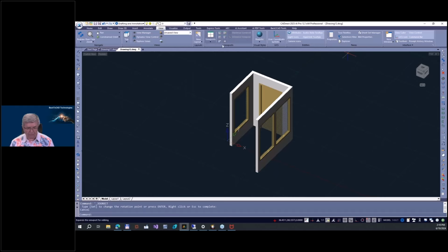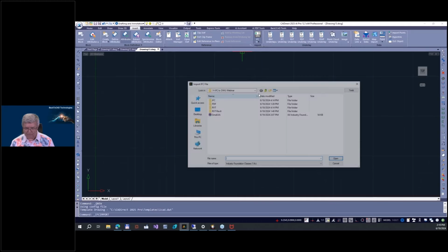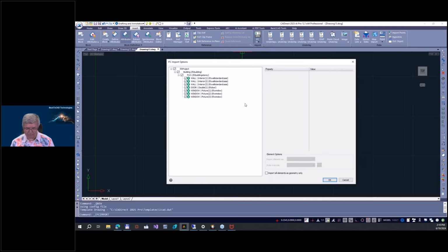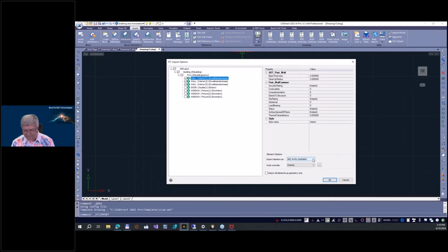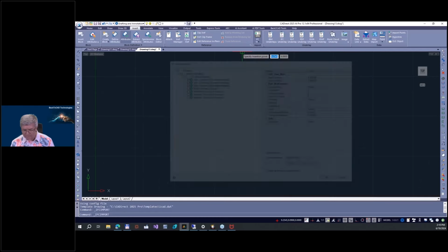If you want, you can go here again, new drawing. You can go here on Insert, IFC in, okay. And you can go here, again this is a small IFC, and tell, no, I don't want any windows. I need only the walls, because I am some engineer. I have to make a construction, maybe concrete construction. I need only the walls, and I need this wall as geometry, this wall as geometry, and this wall as geometry. Okay, and here, enter, is done.